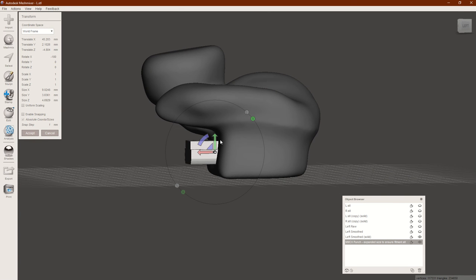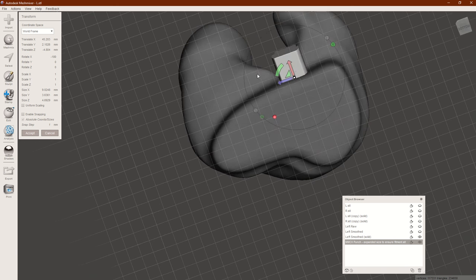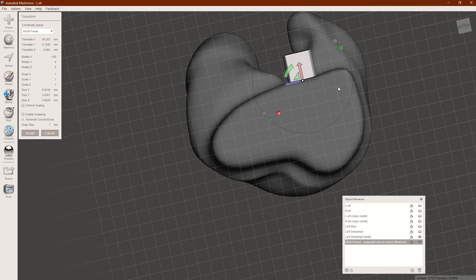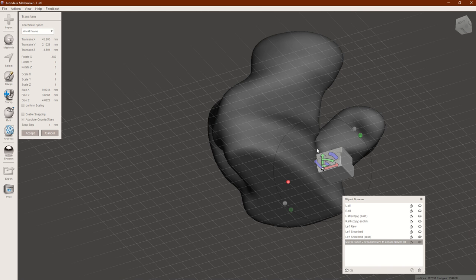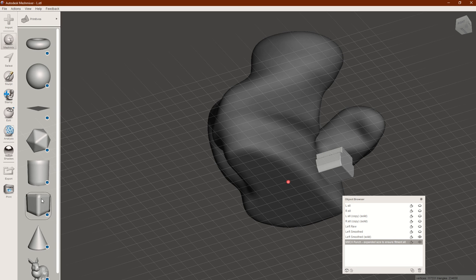Now the problem is this jack, if I were to glue it in, it'll be sticking out here. So how do I make this MMCX connector made up to the in-ear monitor in a good way? Well, I'm going to leave that guy there for now, and I'm actually going to add a cube and use it as a place that will create a flat surface that I'll smooth into this. I'm going to do that with MeshMixer. I'm going to hit accept so I can get off of that device. I'm going to MeshMix a cube.